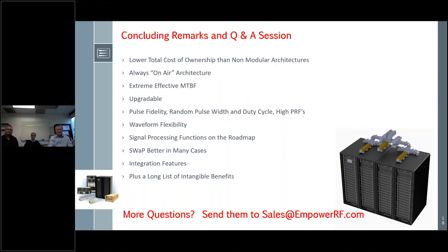Great, that helps. Follow-up was options for Ku band. It's going to be all about devices, Ku band. Yeah, it's the 11, 13. I think the currently available semiconductor devices, power per device is not great. So you don't end up with a lot of power per RF deck. As I mentioned, the work we're doing currently is X-band, so we don't have any designs currently that are Ku band.